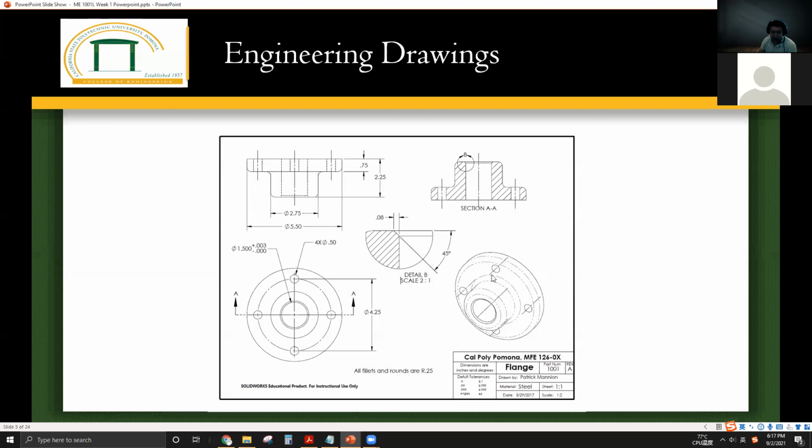Normally the practice is to make a center line of a hole if it's a through hole. That's why you can see from this isometric view there are 1, 2, 3, 4, 5, a total of 5 dashed lines through 5 circular holes.